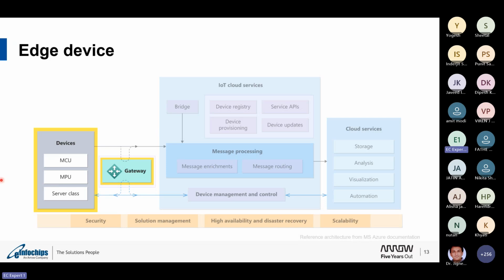For example, today there is a service called Azure Sphere, which is a secure high level application platform built for communication and security for internet device protocols coming from Microsoft. It is comprised of a secure connected MCU, and it contains the capability for a Linux-based operating system which can communicate to the cloud. So you can use an open source RTOS, or you can use Azure Sphere, which simplifies the integration with the cloud and building your device.